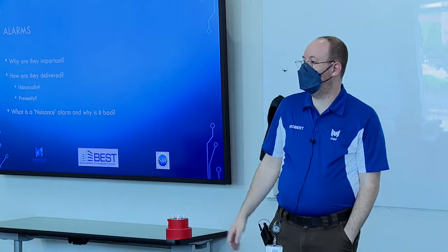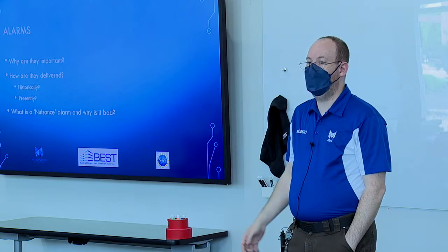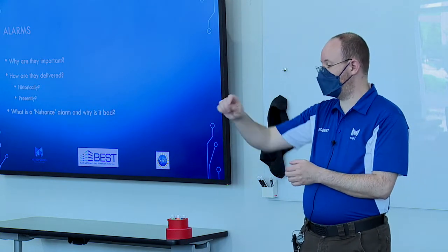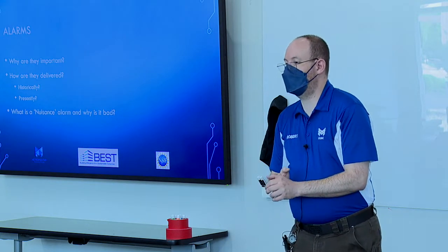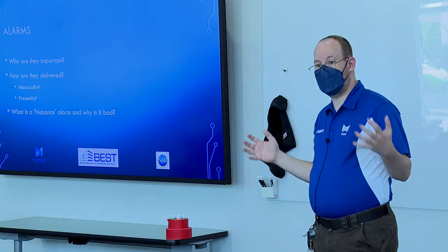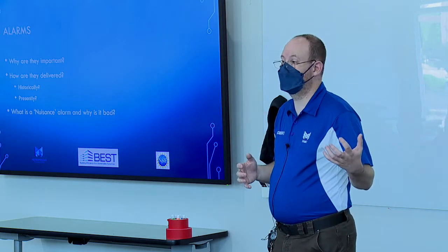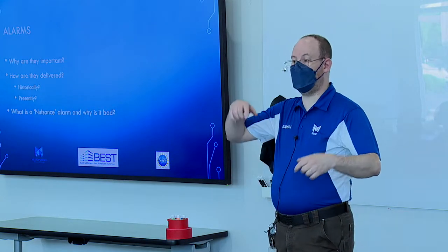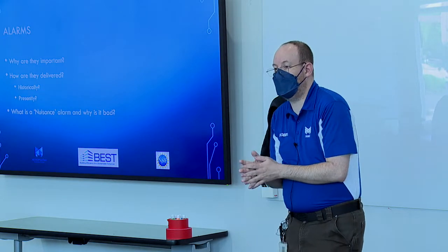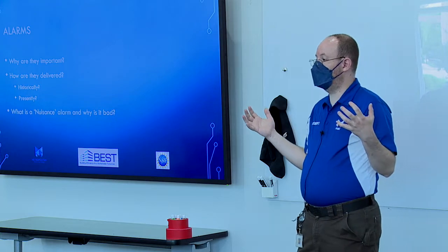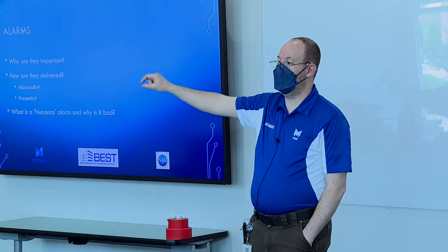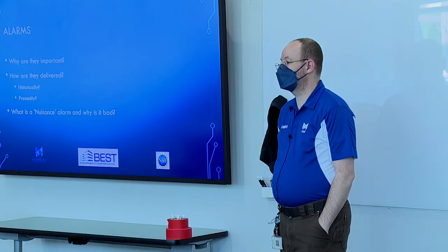And part of the operator's job every day was to come in and look at the list of alarms and start addressing them, hopefully. Some of them were just recorded. Ah, this went into alarm again, sort of thing. Okay? Sometimes we also would have a printer attached to that workstation or attached to that system. And when you got an alarm, it would automatically print off the information about that alarm. Maybe it was formatted in such a manner as a work order, or sometimes maybe it was the chilled water pump 2 is broke, dummy messaging. Okay?